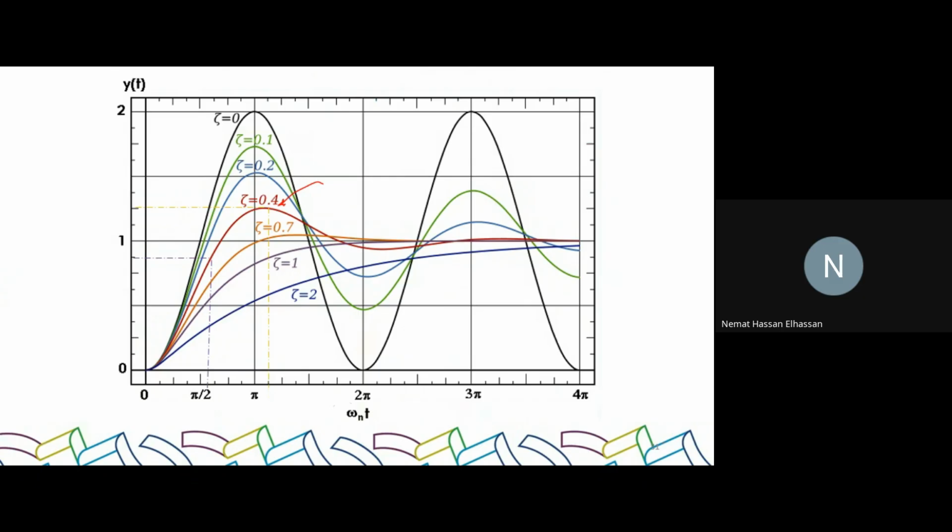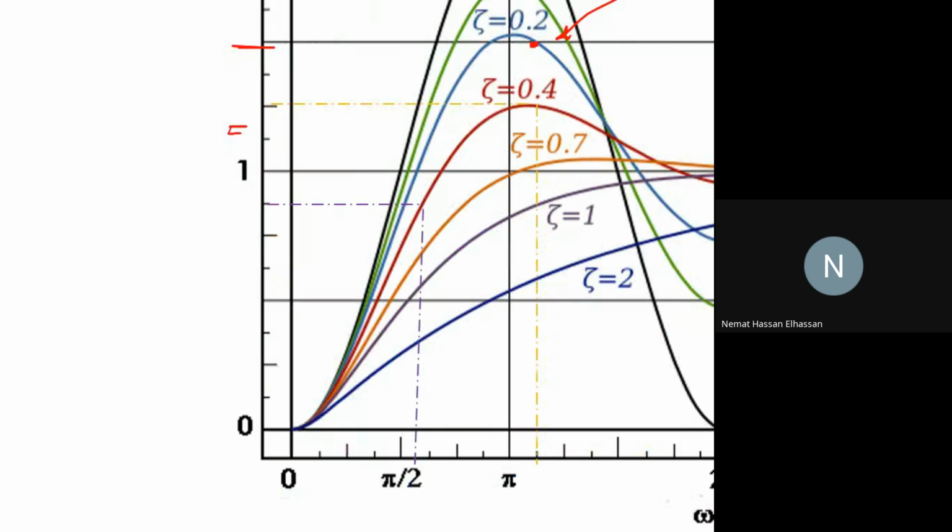So now I know which zeta is. I can calculate the percentage overshoot because this is the unit step response. When the input is 1, this is the highest peak value, which is here, right? So let's calculate it, but I want you to pay attention to one small detail. If you look at the scale, it's not decimal. It's not 10 points to each measure point.